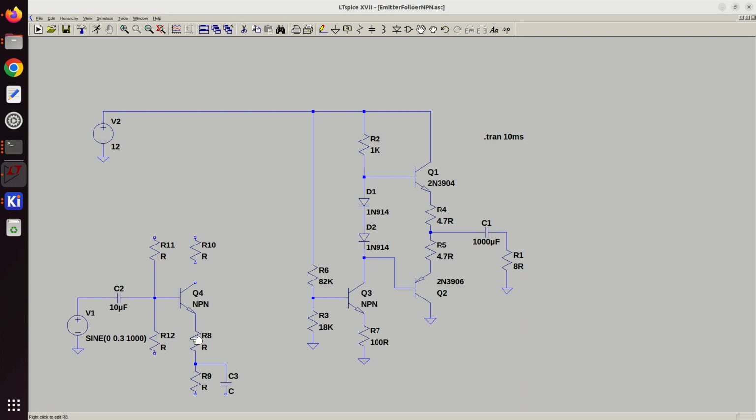Then we'll actually build it and see how it all works in the end. I'm going to put these straight up here for now, but in reality I would isolate these. I'd put a resistor and a capacitor in here just to stop this drawing a lot of current, and you're going to find you can get motor boating if you don't isolate them.